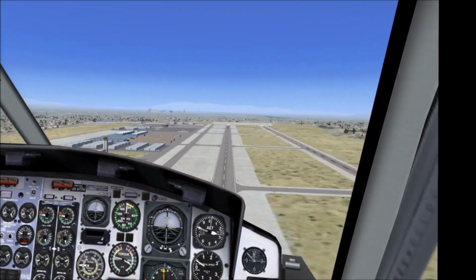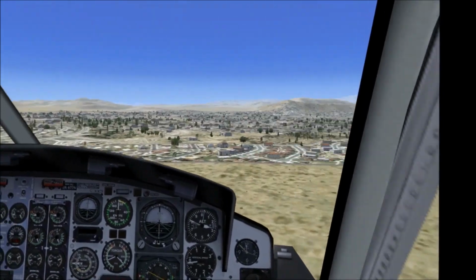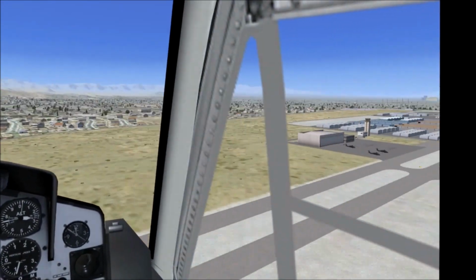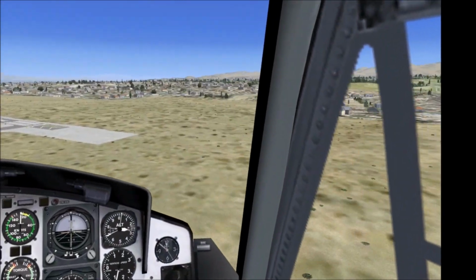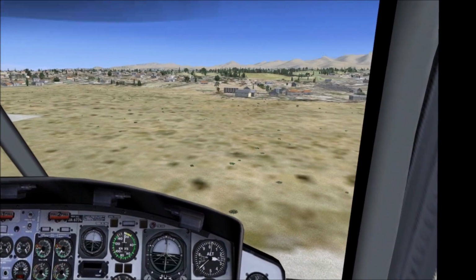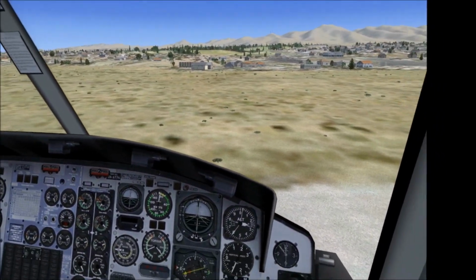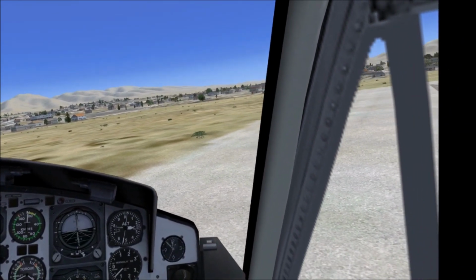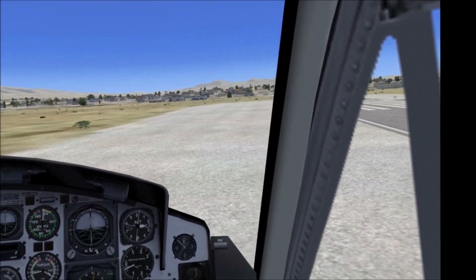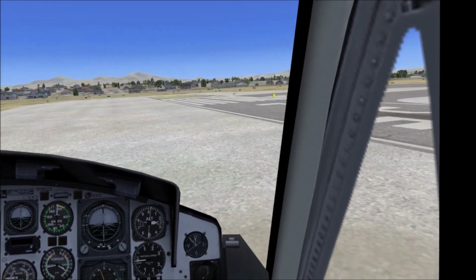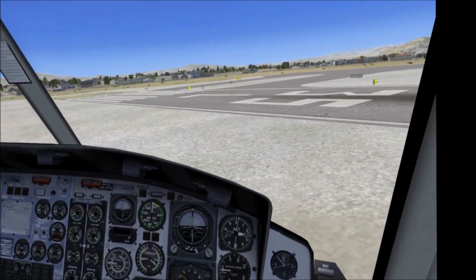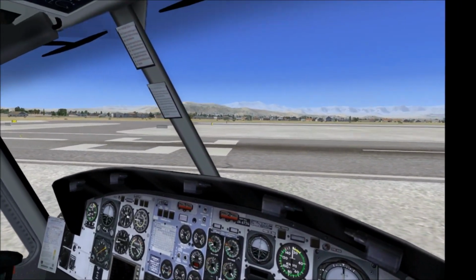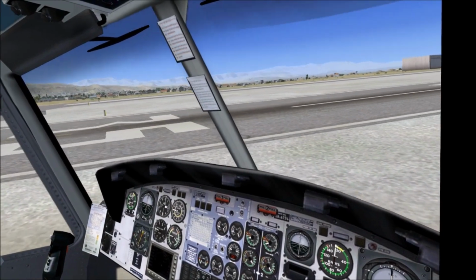So that's okay. Before you guys get sick, I'm going to lower the collective. I like that we get an increase in the rate of turn with an increase of power, but it actually seems to be more altitude driven, not power driven, because as we descended there, we slowed down almost immediately. At that low power setting, as I descended, that rate of turn stopped almost completely. So that's actually pretty promising. I like the response.